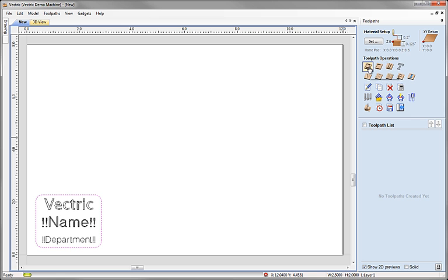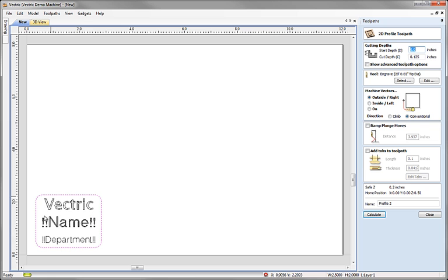So I'm going to use the profiling toolpath strategy to make my cutout pass. So I click that with this boundary selected. I'm going to select my engraving tool here, which is a small fine-tipped engraving tool.